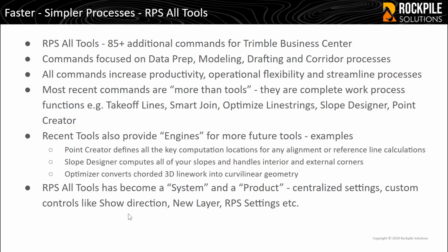Slope Designer allows you to create offsets and slopes, offsets and elevations, offsets and slopes to surfaces, offsets and slopes to finished design levels. You can also use our point creator function to actually create points along feature lines.